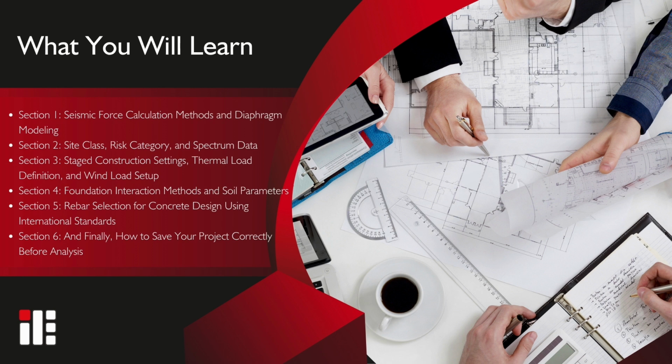Now that we've completed the structural modeling, it's time to prepare our project for analysis. In this video, I'll guide you through ideCAD's analysis settings, where we'll define seismic parameters, site conditions, wind and thermal loads, diaphragm behavior, and more, all aligned with ASCE 7-16 and other international standards. We'll also review rebar selection and saving protocols, so everything is ready for a successful structural analysis.